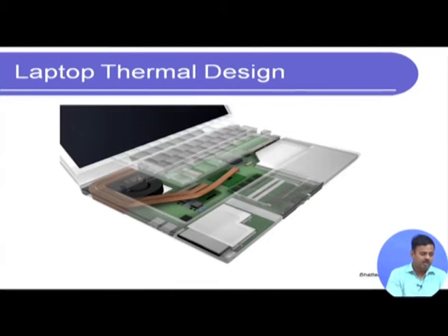So therefore, I can put the fan and heatsink at one corner or one side of my laptop where I have a cutout in the motherboard. That is where I have a fan which blows air through this finned heatsink, and the exhaust air comes out. In any of your laptops, if you look through the exhaust vent from where hot air comes out, you will be able to see this copper or aluminum finned heatsink. And there is actually a fan just upstream of that which is blowing air.